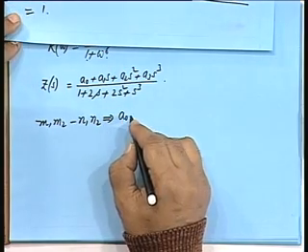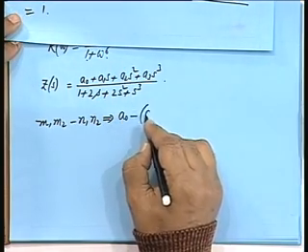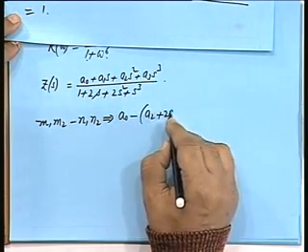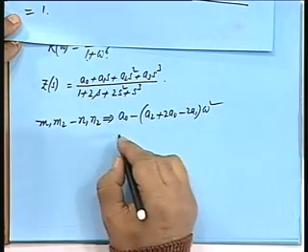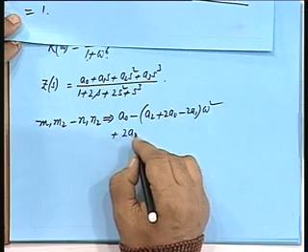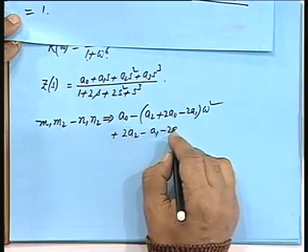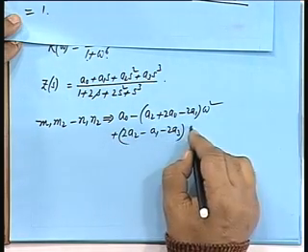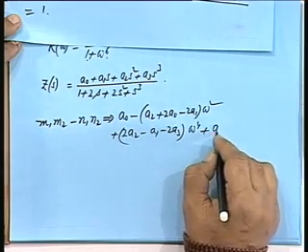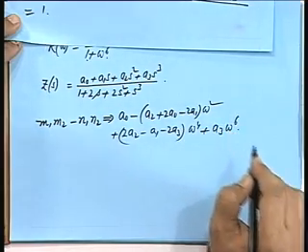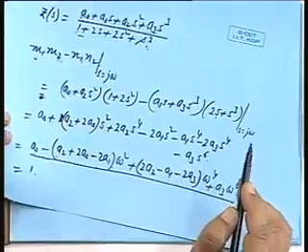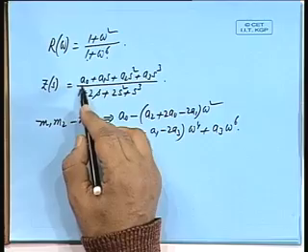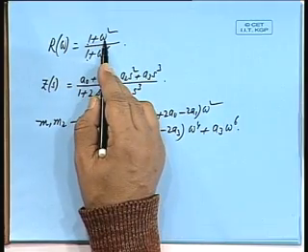A0 minus A2 plus twice A0 minus twice A1 omega square plus twice A2 minus A1 minus twice A3 into omega to the power 4 plus A3 into omega to the power 6. Okay, this was our numerator, is it not? M1 M2 minus N1 N2, starting with this. Now that has to be equated to 1 plus omega squared now.